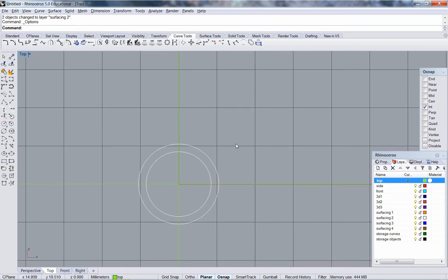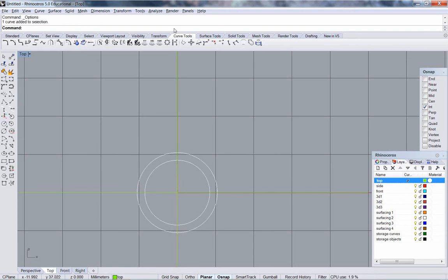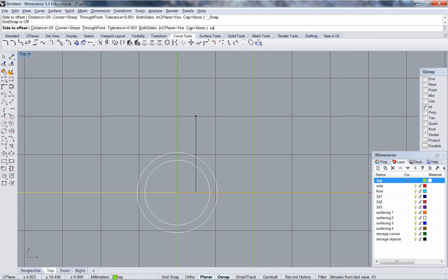My band is half of that. So if I put my center line here, I've got plenty of room. So I'm going to do that. Bring a construction line over. To catch this grid intersection, I'm going to turn on grid snap. I'm going to do the same thing for my top view since it's a static width band. I can also turn grid snap on and off with S enter, which is how I'll be doing it from now on in our tutorials. Come up, and there we go.